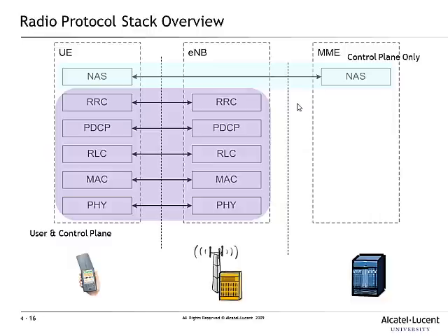Remember, the air interface is always the most difficult transmission link over which you've got to get your information. If you work from the bottommost layer upwards, the bottommost layer is the physical layer, where you package information into these OFDMA symbols and subcarriers and so forth.